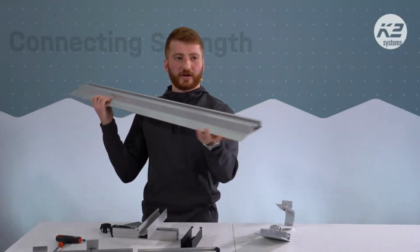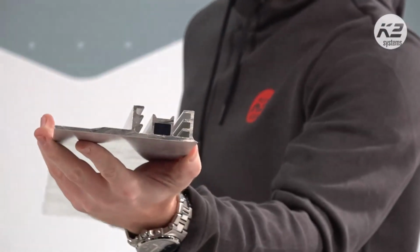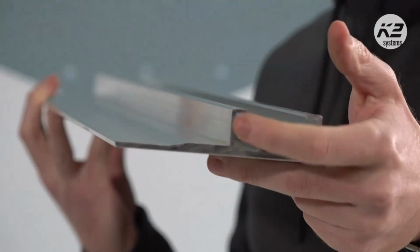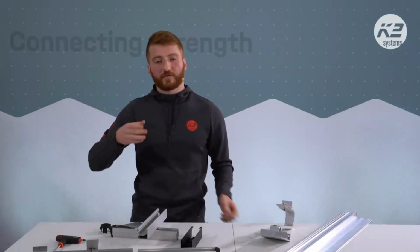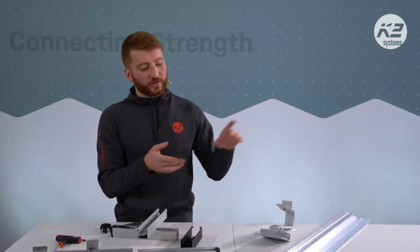Why do we use the single board? It looks like this. And as we see, here is a channel of M. Here we can install our hooks on 3 elevations also. So where do we use the single board? Imagine we have a roof and at the end of the roof we needed to install one roof hook, but there is no rafter there. And we needed that. It's a technical necessity. We have a long cantilever and we have to fix one hook there. That's why we use the single board.